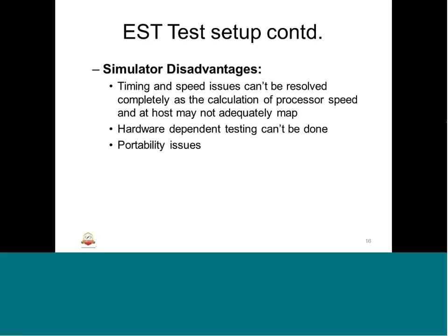One thing I remember in terms of simulator disadvantages is that, for example, the target system may have an 8-bit data bus between RAM and an unpipelined or memory mapped processor, and the host may have a pipelined processor, and it could be 32-bit. So there is a difference between the target system and the host.